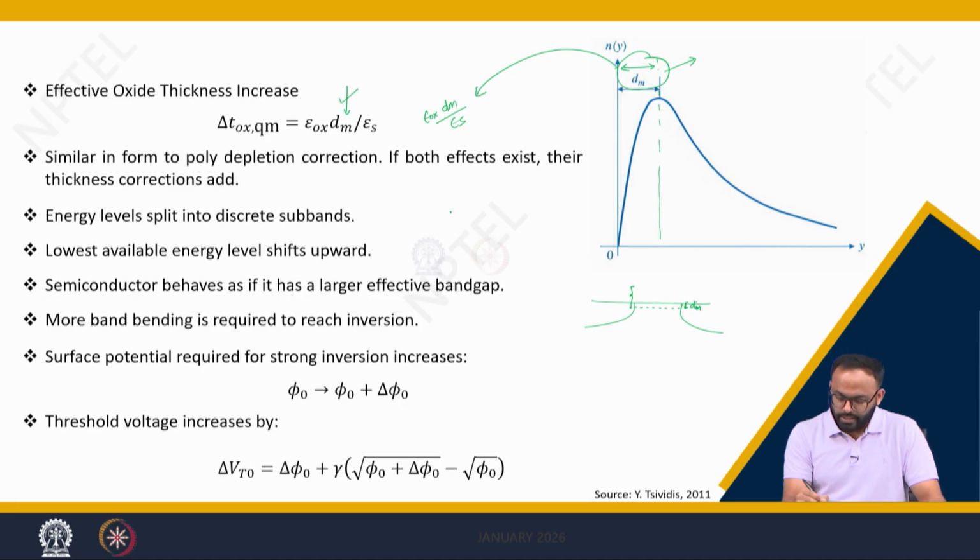The second effect is the increase in threshold voltage. As we have discussed, the bands in the triangular potential barrier are now sub bands, and hence it will increase the effective band gap, and because of the increase in effective band gap, Ni decreases, which means the Fermi potential decreases, which means you have to apply more effort to induce the same amount of inversion charge.